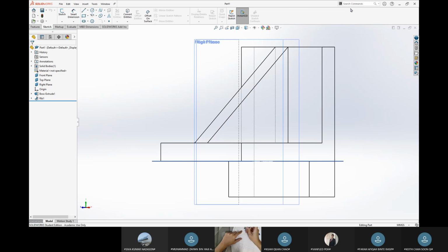But since I don't have anything, you can draw it from the next line over. And I'll just extend this line all the way across. Make sure you measure it's 12 mm all the way through across the front. Okay. So this is the shape.